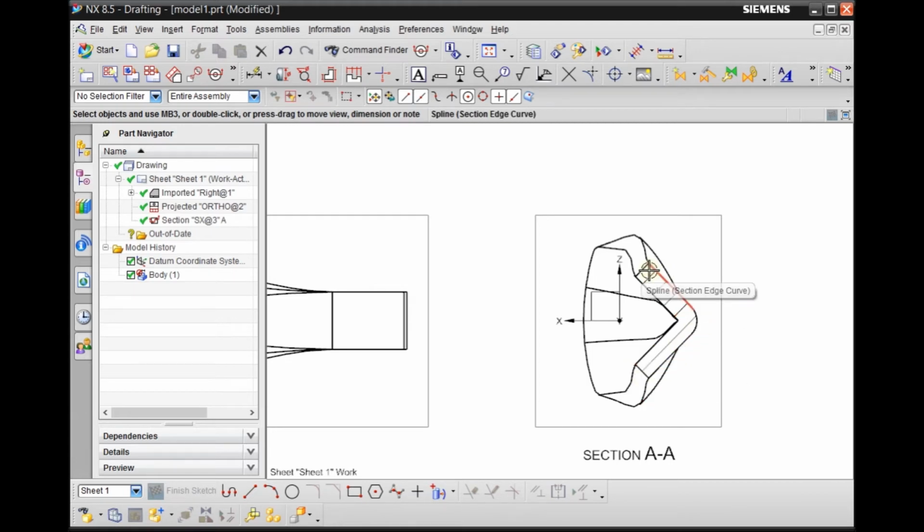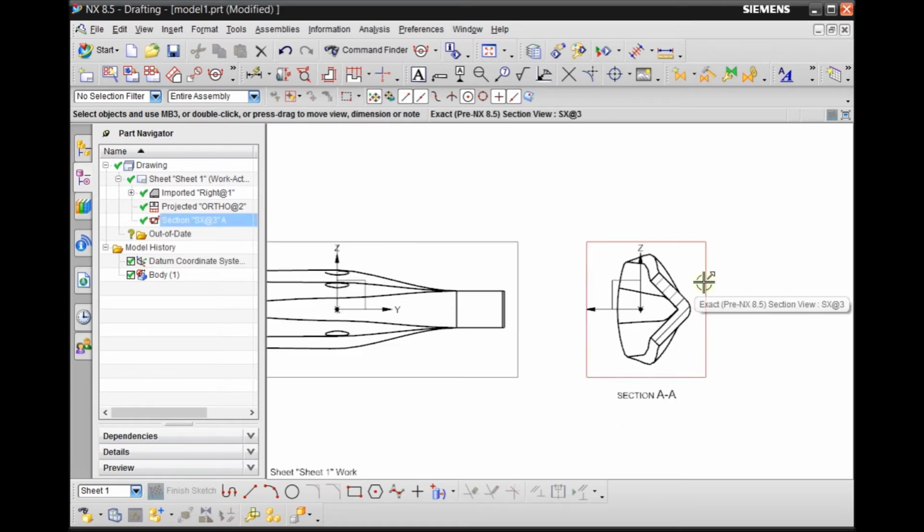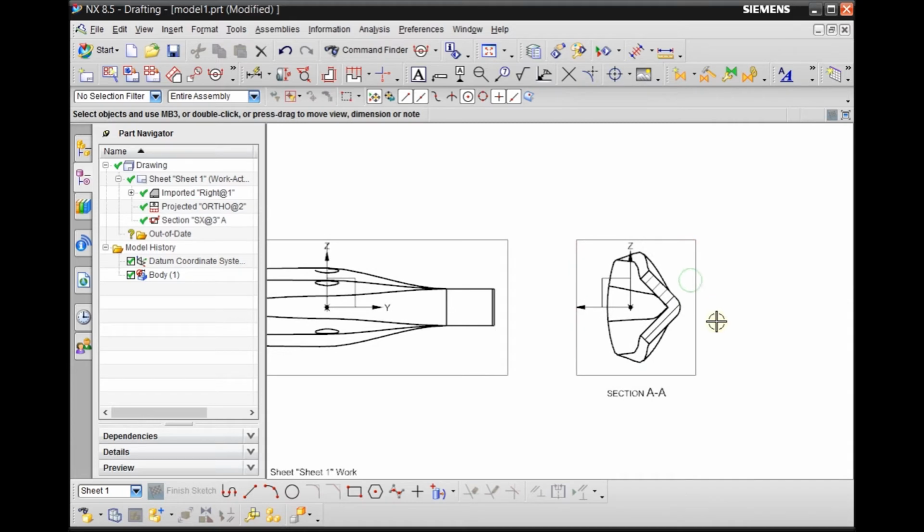Sometimes there'll be a mess, and sometimes if you get rid of this background here, the cuts on the surface will not even show up. So the key point is you convert IGS to solid, then you come here, and you can make clean cuts.